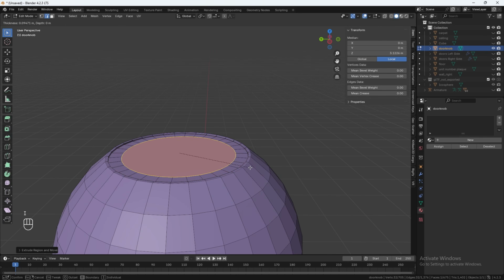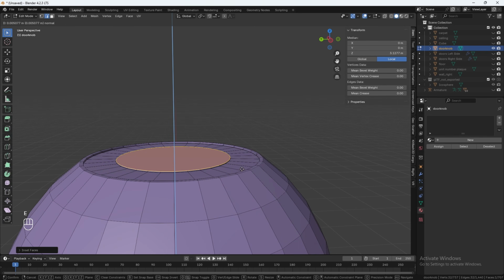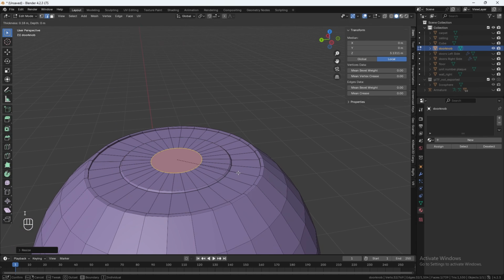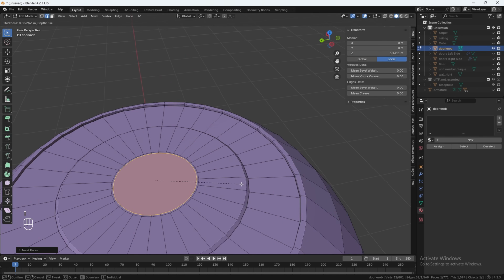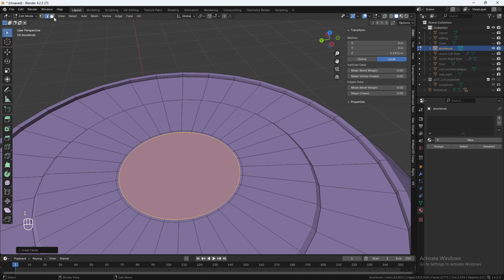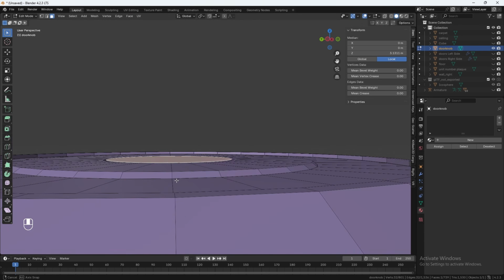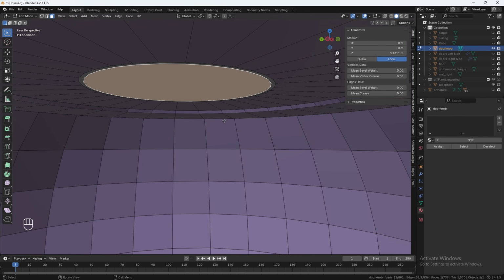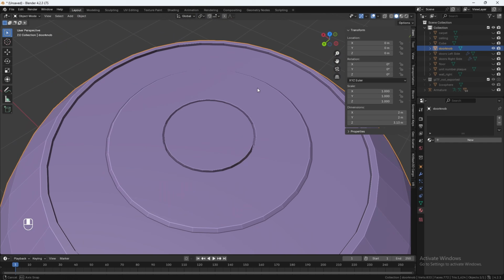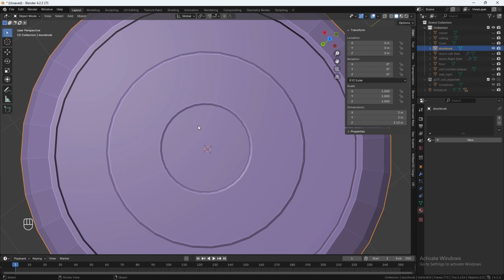I to add in another face. E extrude up. Then I to add in another small face here. Another I. Then you can use the Face Select tool. Hold Alt, click here. And then X, delete faces. Then you can just select this face, go inside, and hit E to extrude down. Okay, now we just need to add a keyhole at the top here.